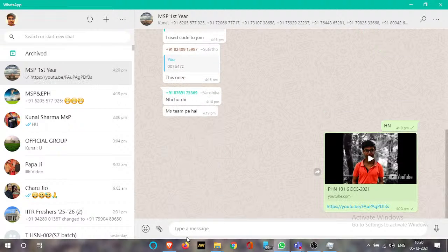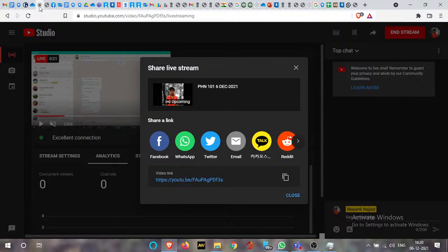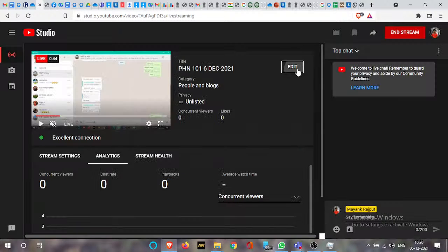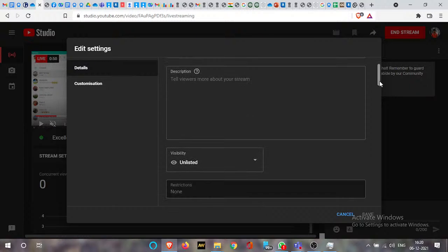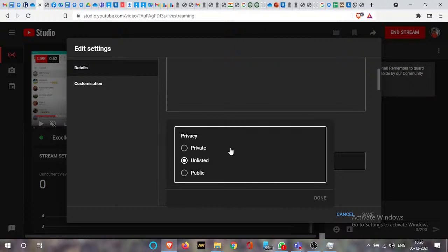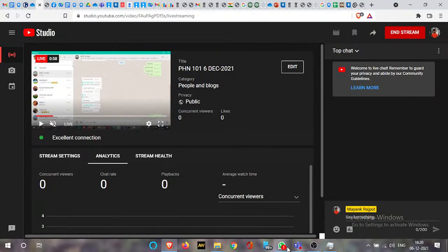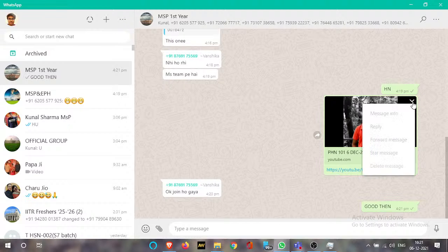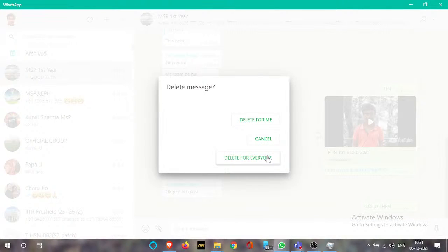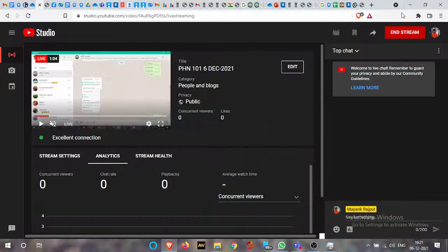And now, what are spin valves? Spin valves are basically two ferromagnetic layers separated by a non-magnetic spacer layer. Now this non-magnetic spacer layer can be a metallic layer or an insulating layer. If it is a metallic layer, then this structure is called a spin valve. So you see here, forget about this layer for a moment. This is one ferromagnetic layer and this is another ferromagnetic layer, and there is a spacer layer in between. Now this spacer can be metallic. If it is metallic, then it is called a spin valve.